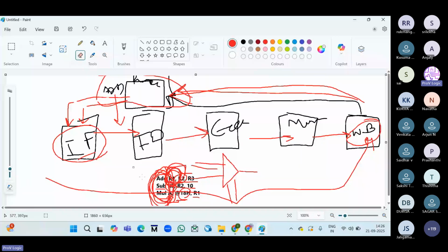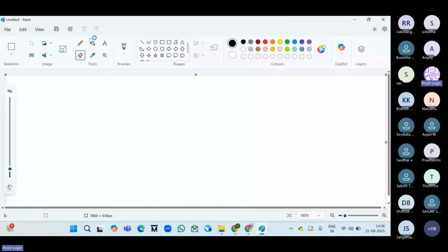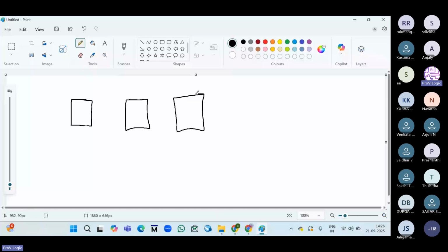So how many of you know about the pipeline? What is meant by pipeline? Pipeline means executing stages parallelly, somewhat parallel. Before, I have drawn there are 5 stages. One is the instruction fetch stage, another one is the decode stage, then the execute stage, memory access stage, and write back stage. So in a RISC processor, to complete one instruction, it nearly takes these 5 stages.